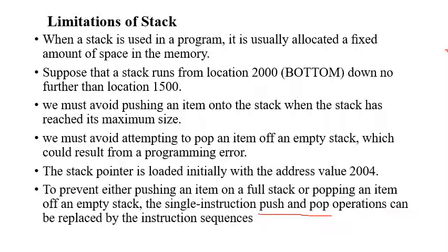So for example, in order to avoid pushing an item onto the full stack, you can compare the stack pointer with 2000. Once the stack pointer becomes 2000, you are not supposed to push the data.